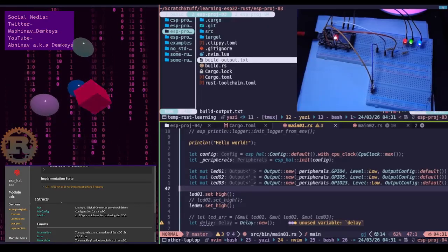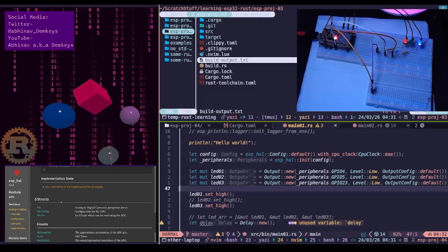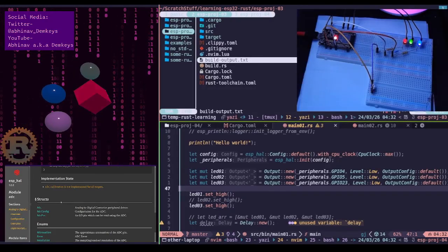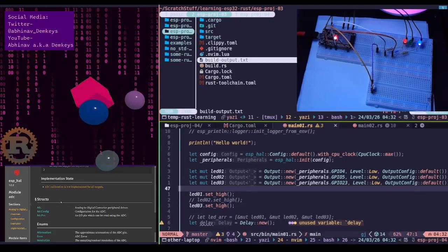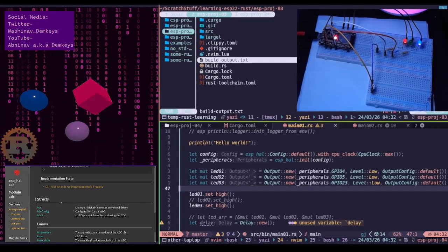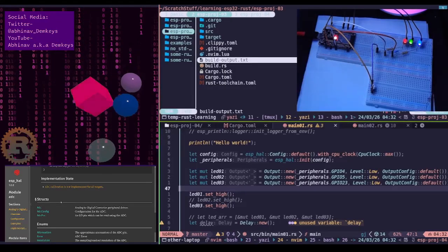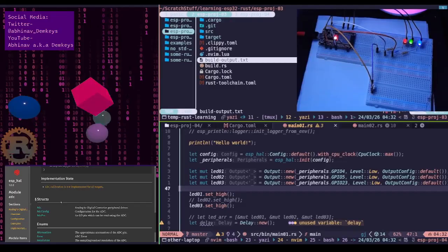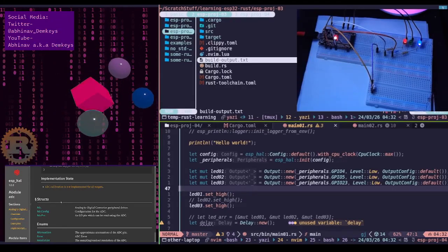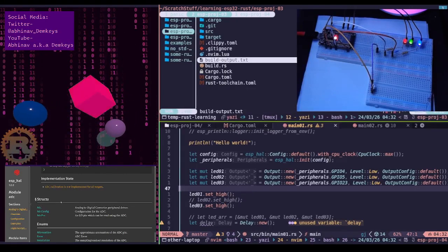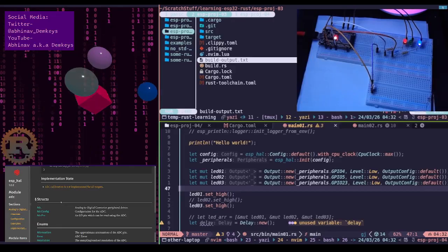The fixed voltage divider. Imagine two equal resistors, 10K each, connected in a row, as in series, from 3.3 volts to ground. All right. At the top, which is VCC, the pressure is 3.3 volts. The first resistor, the current has to fight through this. Since R1 and R2 are equal, the electricity spends exactly half of its energy here.